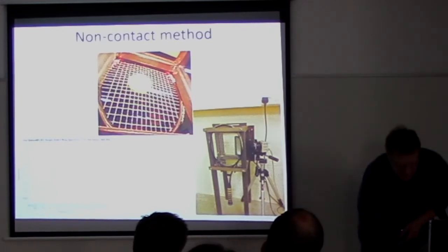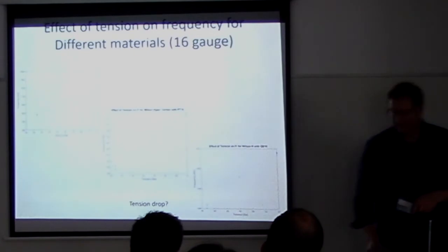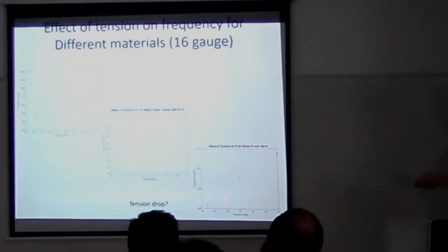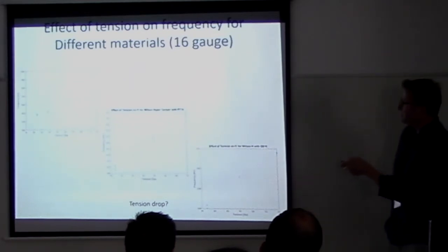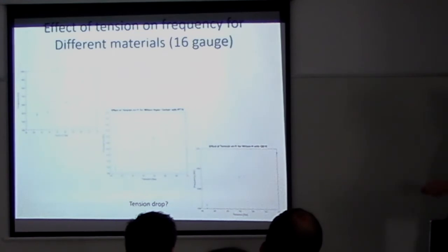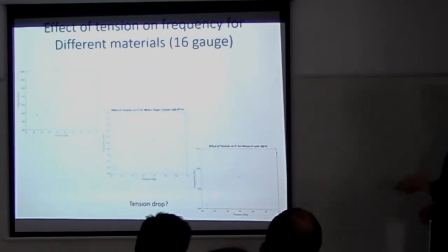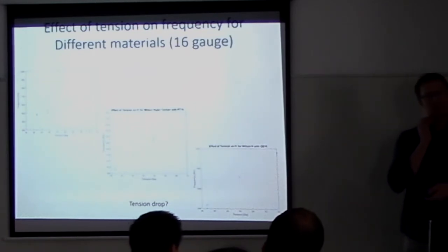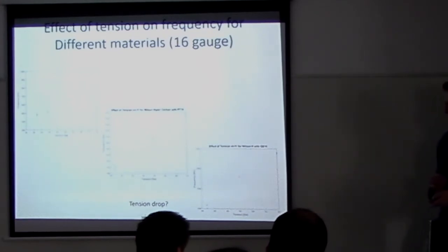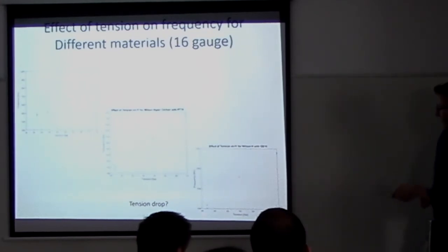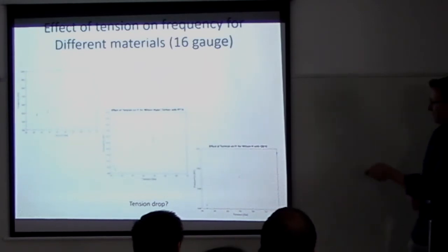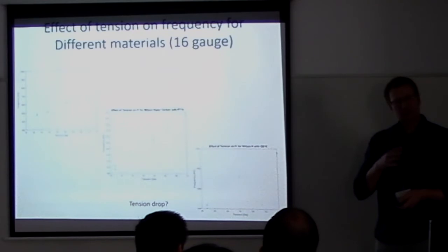And then we decided to proceed along with this method by looking at a response of frequency against tension. There's natural gut, we have polyester, and this one which is obscured is synthetic gut. We have sort of marginal differences, and all of these results are taken immediately after stringing, plotting the frequency, because we know that the frequency is proportional to tension, and we can then start to compare whether this method has given us something that adjusts to these fine variations.